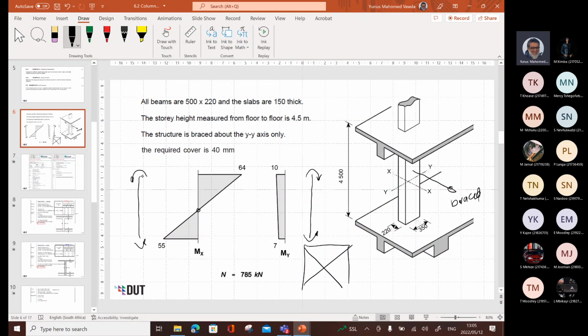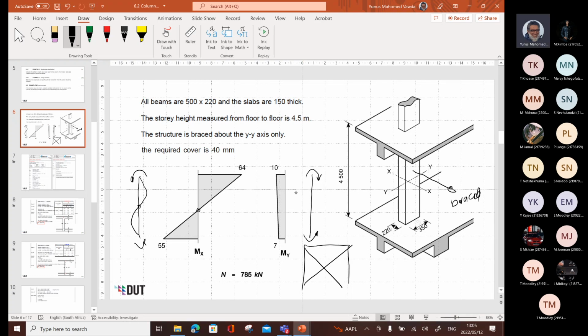So you can look at it like this in terms of buckling. There's a point of contraflexure. So there we have it. Whereas this one, when you bend it, it's just going to do that. Fixed or pinned or whatever, I'm not too worried about that, but just understand the principle. So that's single curvature, right? So I've got the two there in one.